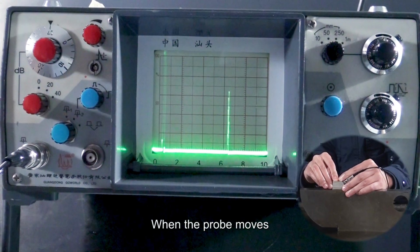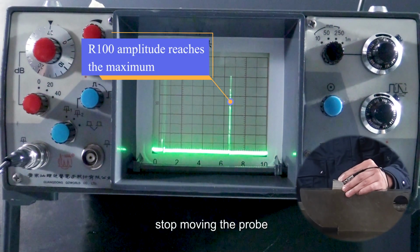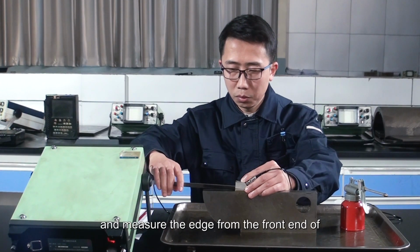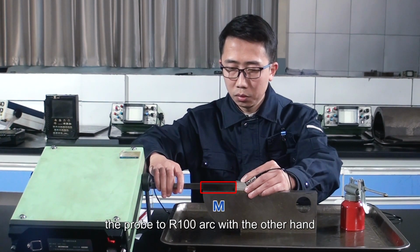When the probe moves to where R50 and R100 reach maximum amplitude, stop moving the probe, press the probe with one hand under constant pressure, and with the other hand measure the distance from the front end of the probe to the R100 arc edge, recorded as m.